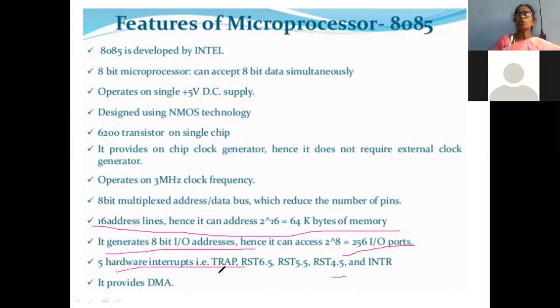Whatever information is to be given to the output device or slow peripheral device can be transferred through DMA. The DMA takes over and transfers the data to the slow peripheral device, so the microprocessor can go for another execution. Is it clear? What is the use of a DMA?